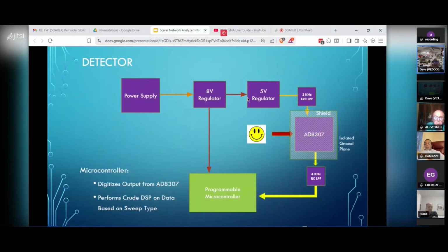Now, this splitting up of the regulator, because the 8307 needs 5 volts to run, I think Kelly did, and I think he did it more for heat dissipation, because to go from 13 volts to 5 volts, that poor 5-volt regulator is going to be dissipating a lot of heat.